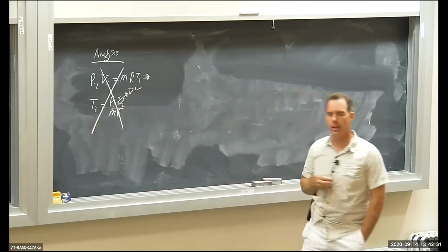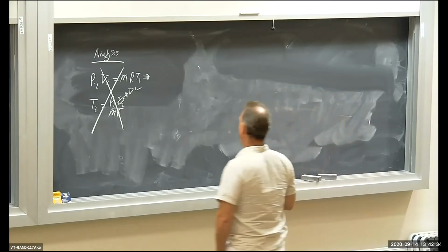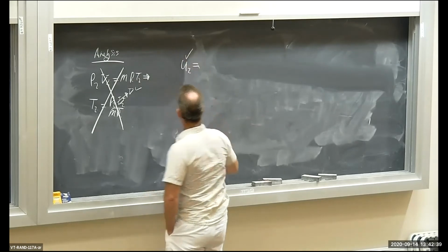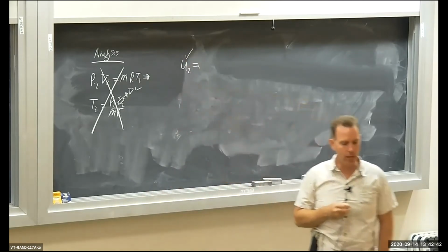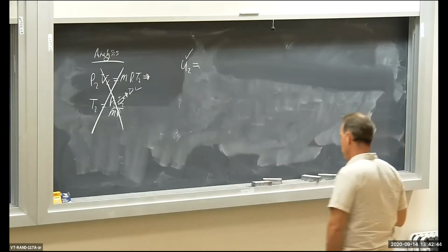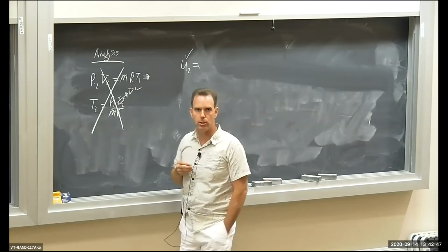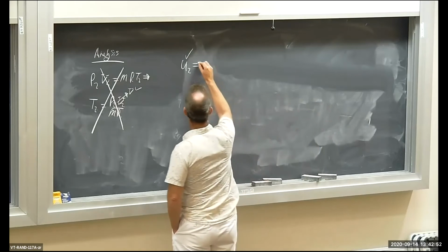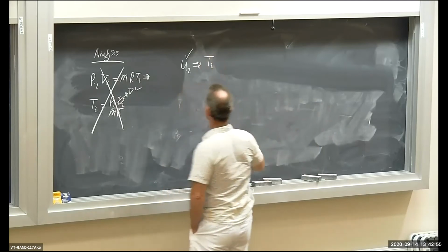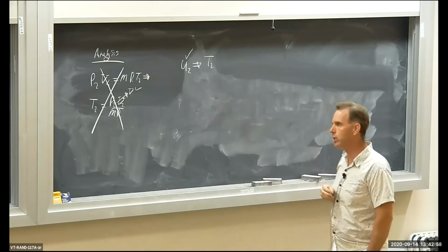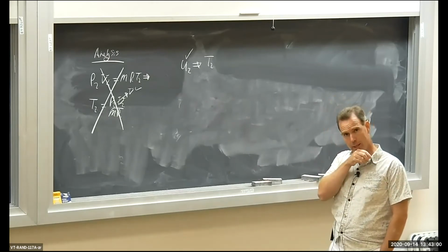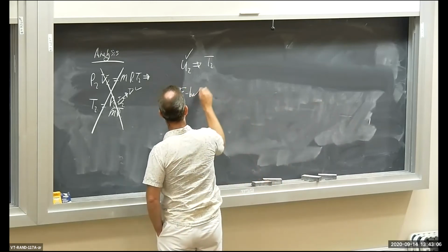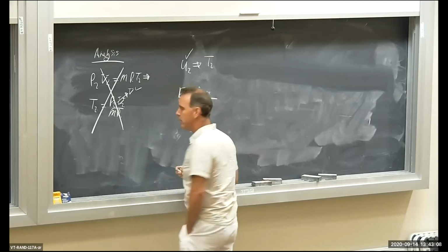What's another way we could do it? If I have the internal energy at state 2, then I could go, let's say, to an air table and back out the temperature T2. So if I have U2, I can get, in theory, T2. So how do I get internal energy at state 2? Well, let's write the energy balance.